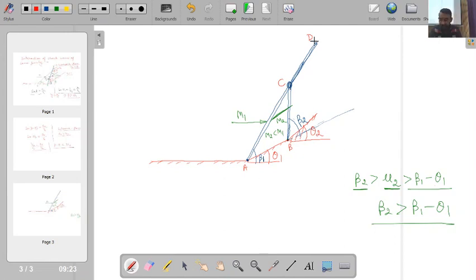Okay, now if you see, this is region 1. After region 1, this is my region 2, and then here I will have another oblique shock wave, so here I will have more deflection. So say this is my region number 3. Okay, and in this particular region you can see that flow starts at point 1. If I see in portion CD, in portion CD also flow starts at point 1, and then this flow is also deflecting.